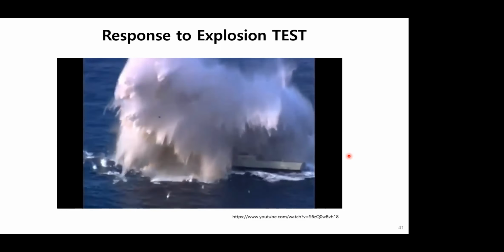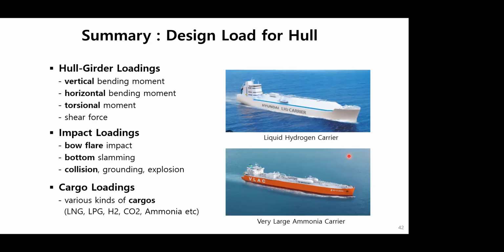Yeah, it's interesting. In summary, main design loadings for hull structures are vertical bending moment, horizontal and torsional moment, and shear force as hull girder loadings. As impact loading, bow flare impact, bottom slamming, collision, grounding, explosion, and so on.